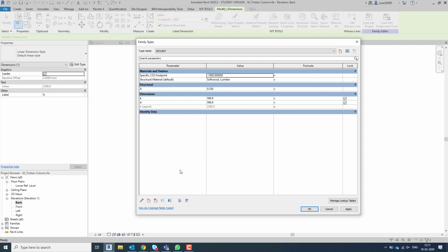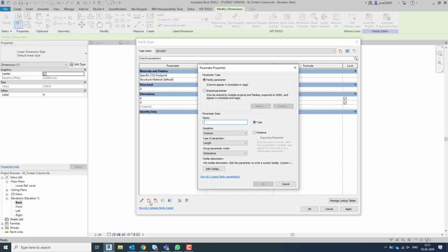This will bring consistency to all the parameters, and they will be schedulable, they will be tagged. This enables the possibility of using the same parameter in different files. Okay, that's the idea behind the shared parameter. So at this point, I'm going to create a new parameter, and instead of being a family parameter, it's going to be a shared parameter.